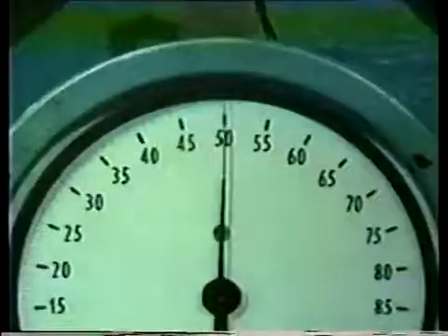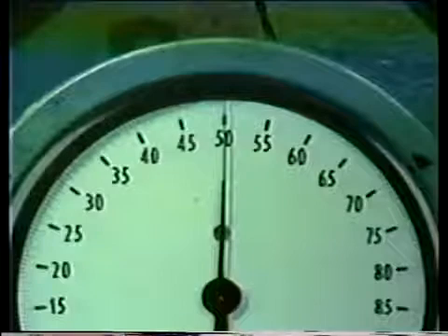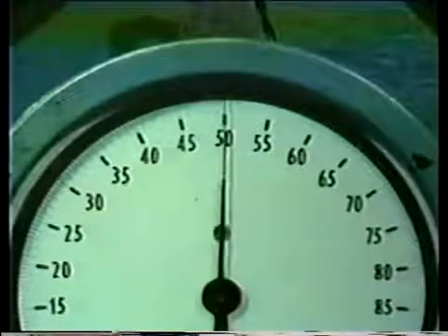By now, the pressure should be starting to compress the manway gaskets. Leave the manway nuts hand tight. Let the boiler do some work for you. Inside boiler pressure will compress the gasket more evenly and make a tighter seal. In order for handhold gaskets to seal properly, the boiler pressure must be higher than 20 pounds per square inch. So, take the boiler pressure up to about 50 pounds per square inch, or 345 kilopascals. At this pressure, the boiler will compress the handhold cover gaskets the way it compressed the manway gaskets.